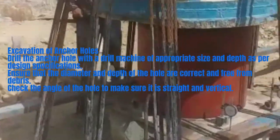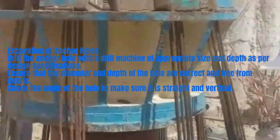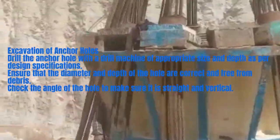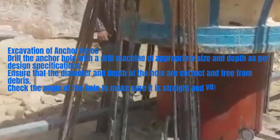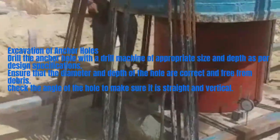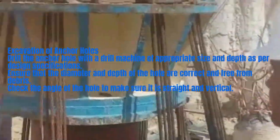There are some factors. For example, during the excavation, variation may be adopted to suit unforeseen conditions within the framework of the specification, in accordance with the engineer's decision. Because when we start excavation for the anchors, we might face a lot of problems. Depending on the site condition, there might be a change in the installation procedure and other issues. The groundwater table and level, everything is a factor, so we have to consider that.